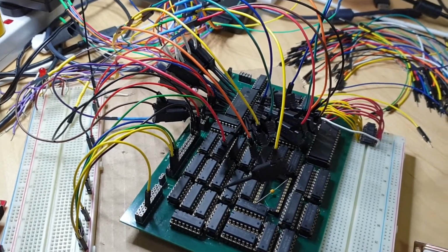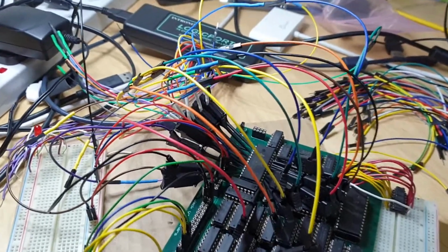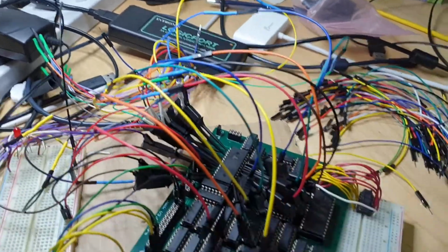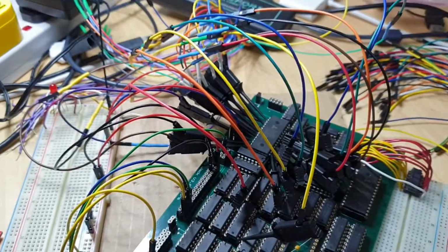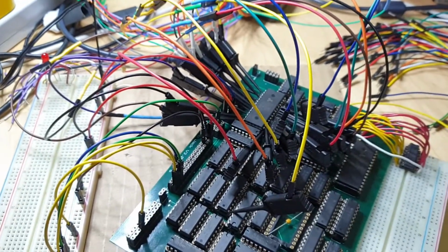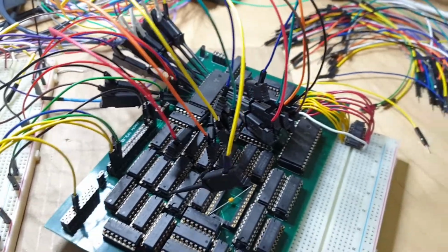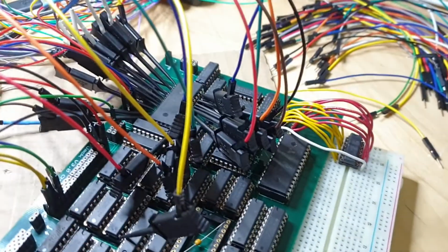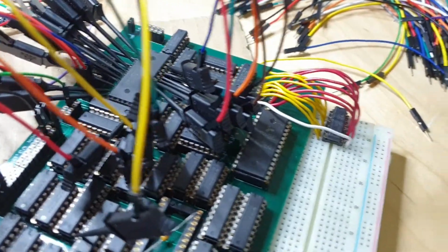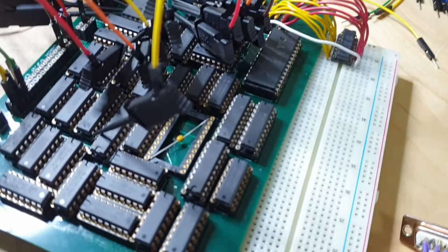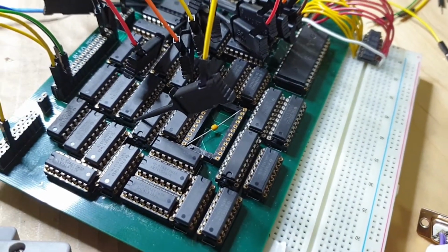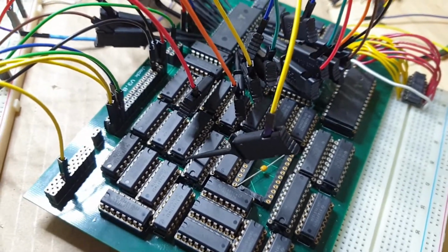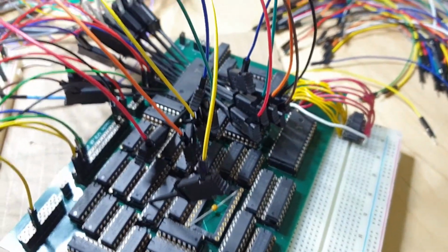Debugging the character plane generation board with the Logic Port 34 channel logic analyzer. I've connected one of the internal RAMs which deals with the character bit plane data. So this is one RAM, the other RAM wasn't populated underneath there, and then this is the third RAM here. This unpopulated RAM here basically returns back a screen containing character 3FF and its related color.